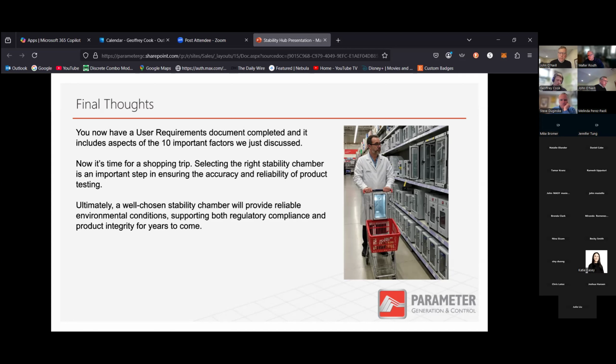You can use diluted bleach. We will sometimes even put bleach in our air handler, disable the fan that's circulating air into the chamber, and simply run the pump and circulate that bleach throughout our entire system just to get that thorough cleaning. Accelerated chambers, they're incredibly harsh environments. They come with their own set of maintenance needs. And a lot of that is very dependent on what you as the user are storing inside the chamber and are allowed to clean your chamber with.